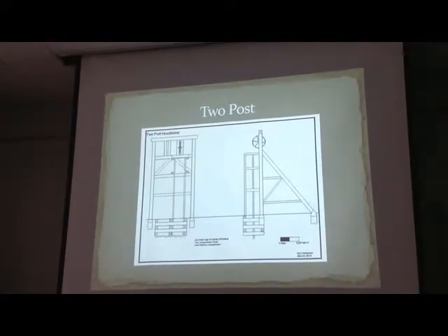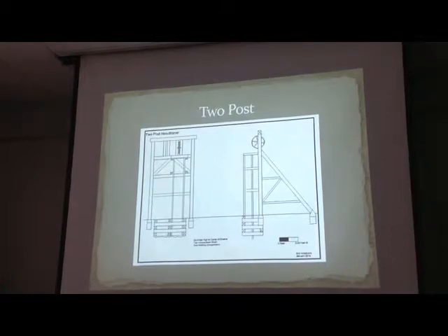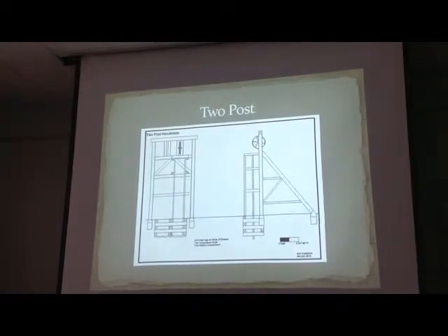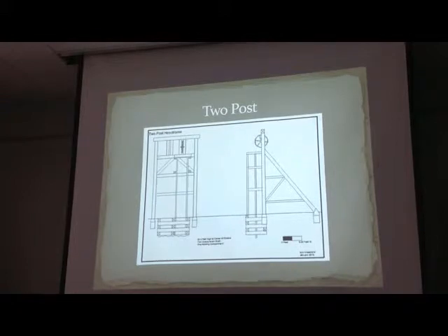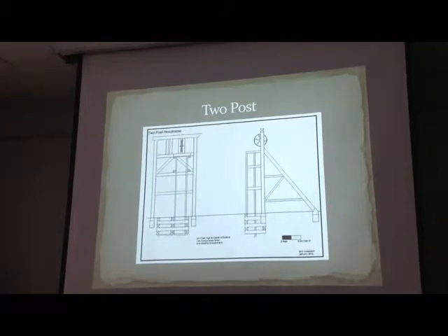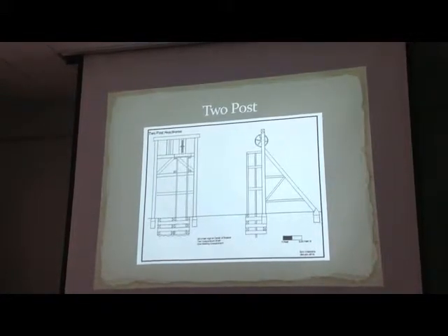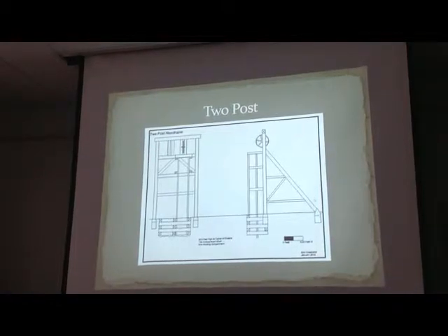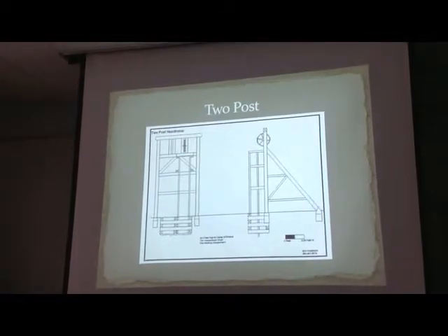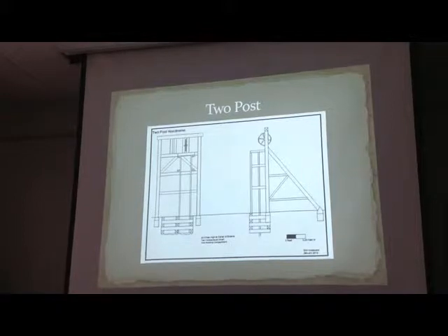But since very few systems are luxurious enough to be able to balance everything out on just two upright posts, the back brace is put in so that the angle of the force of the hoist will fall in between the two legs. Worst case scenario will fall on the plane of the back brace bend and prevent overturning.